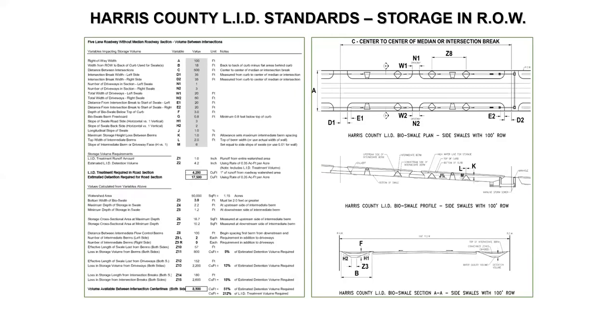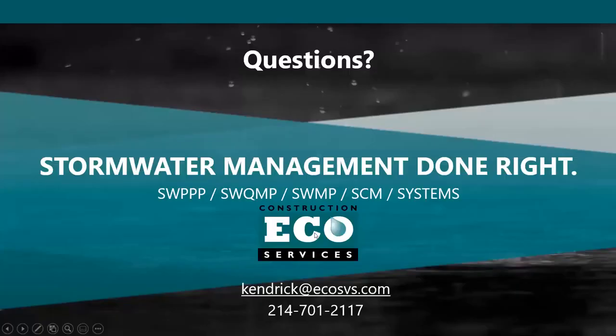But like I said, this works for a normal parking lot in a retail area or things like that. All right, so we'll get down to the rest of the questions here. If you keep adding mulch, will that reduce the ponding requirements? Yes, obviously if you start to raise the surface of your bottom area, it's going to affect the ponding volume. So that's why we like to make sure that they don't just keep adding mulch.